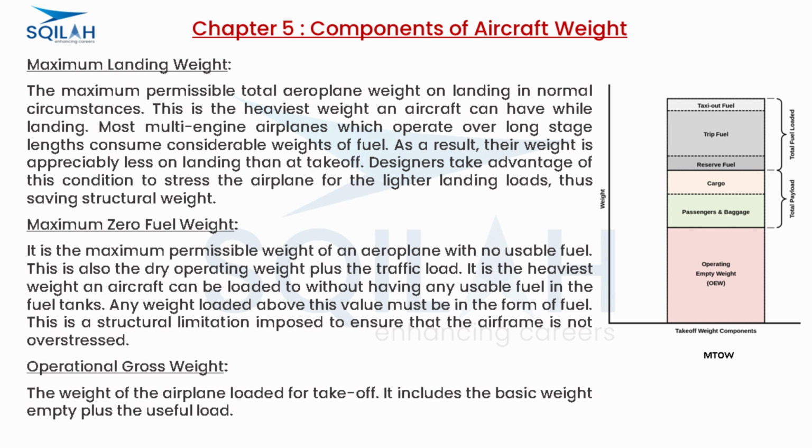This is the heaviest weight an aircraft can have while landing. Most multi-engine airplanes, which operate over long stage lengths, consume considerable weights of fuel. As a result, their weight is appreciably less on landing than at takeoff. Designers take advantage of this condition to stress the airplane for the lighter landing loads, thus saving structural weight.